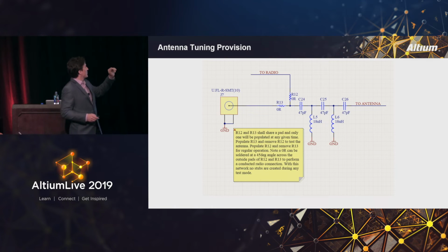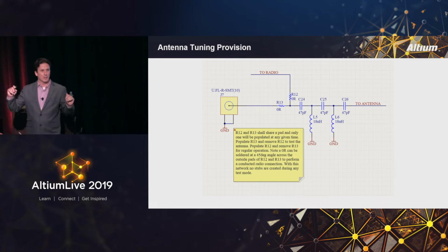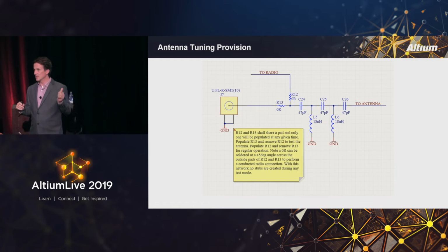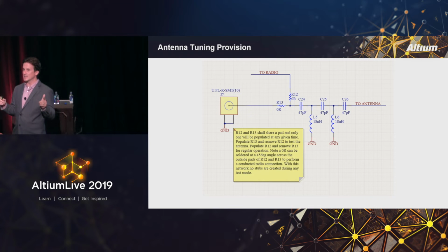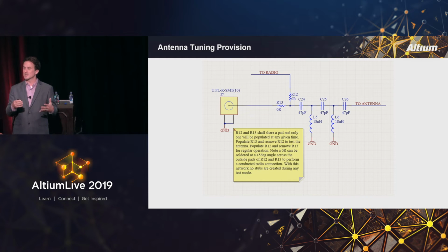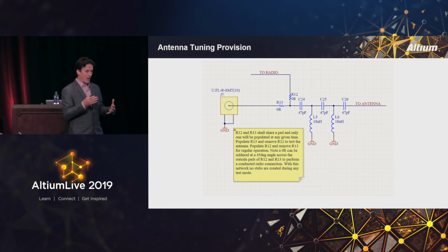Antenna tuning provision. So how many people in here have done antenna tuning? Okay. A lot of times what you see is no one thinks about this, and antenna tuning is not solving a bunch of equations. That's how you get your start. That's how you get in the ballpark of how your antenna needs to be tuned. But after you tune your antenna, what you should be doing is an antenna characterization in an anechoic chamber.